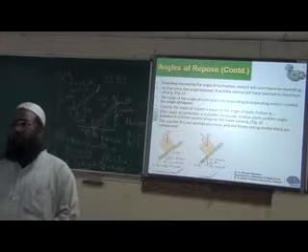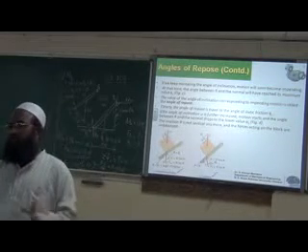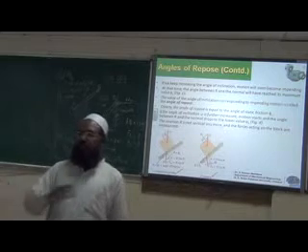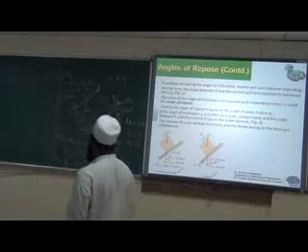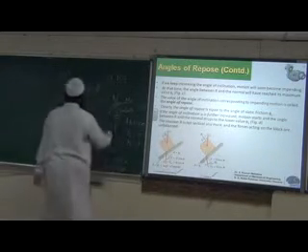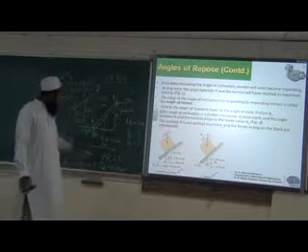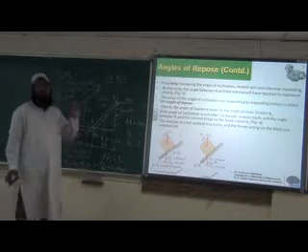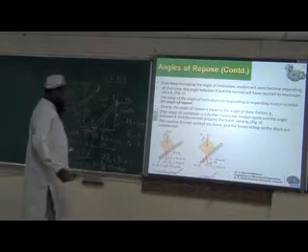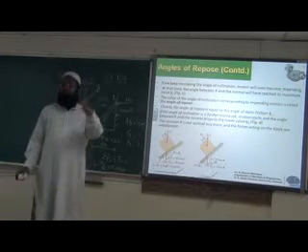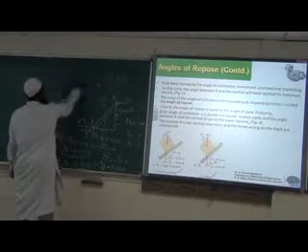If the frictional force required for equilibrium is less than what we get, then we can say it's in equilibrium. If it is more, it's not in equilibrium. So we have to follow 3 steps. Same procedure, similar problem; only we have to check whether it is in equilibrium or not. What we obtain from the equilibrium equations is the frictional force required for equilibrium. What we obtain by the formula mu times NF is the maximum frictional force we can have for the actual mu.